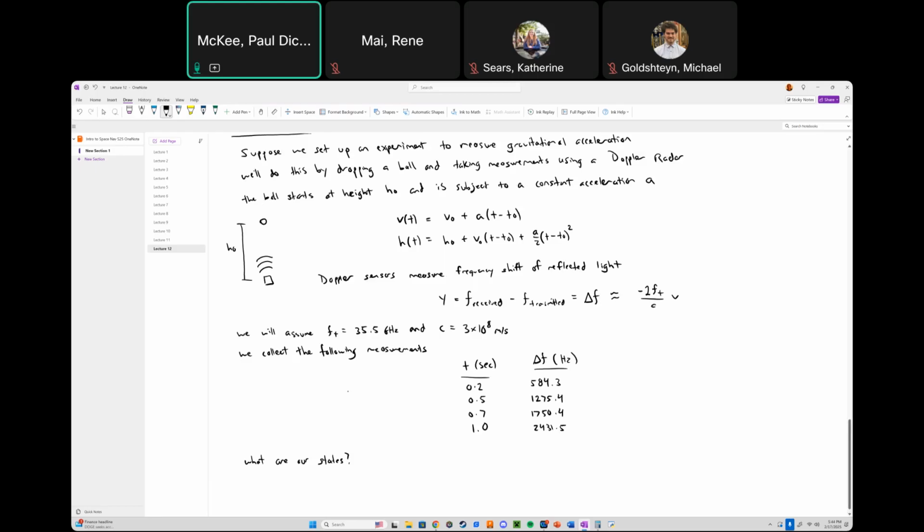So let's say we try to keep track of, I guess position would be height, because this is a one-dimensional problem, and we'll want to track velocity, right? That would be a mistake. And we'll show you later that height is unobservable in this problem. For now, I'm going to ask you to take my word for it. The state is going to be velocity and acceleration. And for now, it's because I said so. Later, we'll show that it doesn't work if you try to do it a different way. So let's try to estimate.